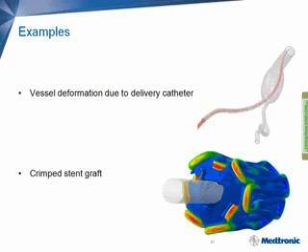We ran the analysis both in Abaqus Standard and Explicit, and after seeing that Explicit had enough solution accuracy, we chose it for running other analyses based on its speed. Complex contact was used, and anisotropic hyperelastic properties for the vessel were also used. In the second example,